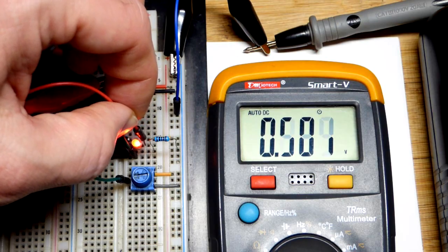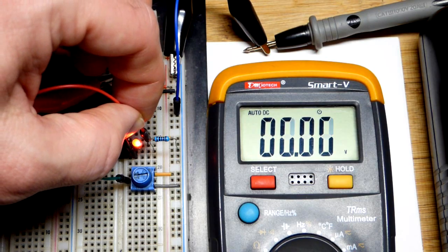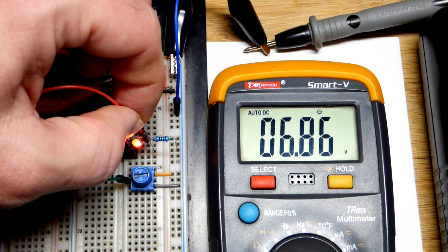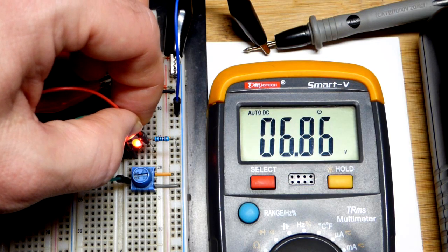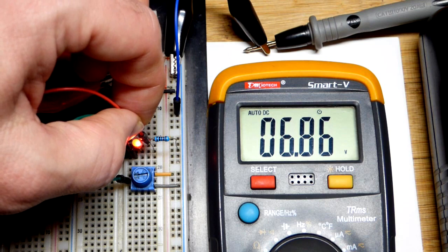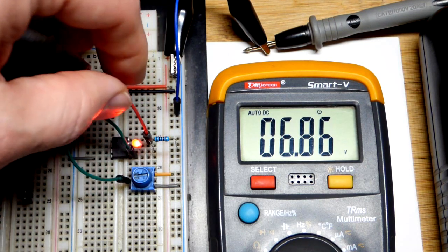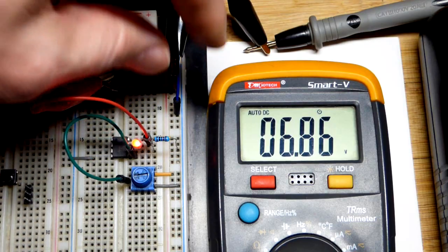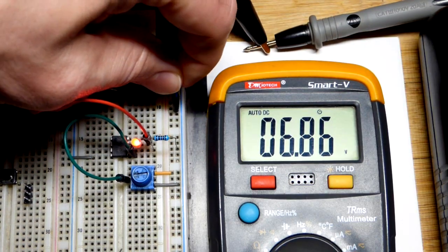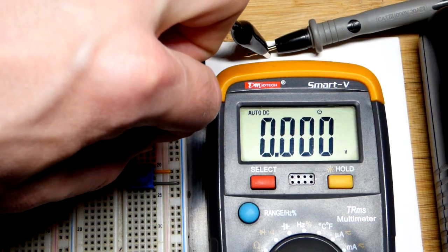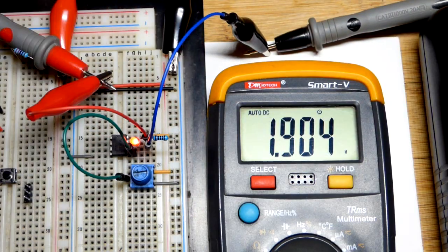We have the red LED, so it's going to be about 7 volts approximately. The trim pot will do whatever voltage is needed. That's one nice thing about these current sources, to cover that voltage difference of the LED right there. So we got that 5 volts, plus it looks like about 1.86 volts. It does go down a little bit at lower currents, below 2 volts. But here we'll measure across the LED directly, about 1.9 volts across the LED.